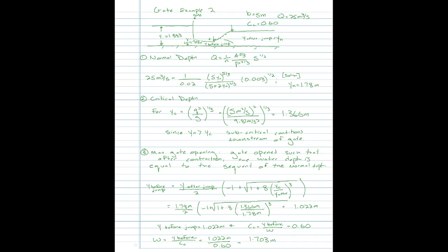It contracts until it gets this depth before the jump, which is 1.022 meters. And the depth after the jump, the normal depth, was 1.78 meters.